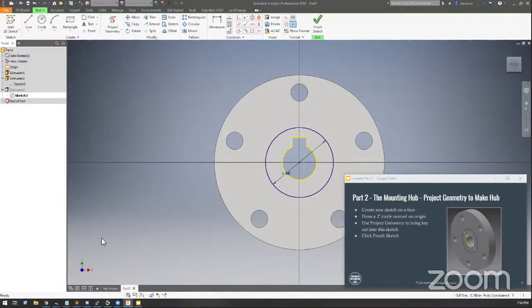and it alters automatically. Okay, so even though there was dependency upon that thing, if that thing changes, so too are the updates to the dependencies. That's another very good reason, because otherwise, if I wanted to make that change and both sketches had that math in there and dependent upon the dimensions that I assigned in that sketch, I'd have to edit 2 sketches to be able to make the key change. And I don't want to have to do that.